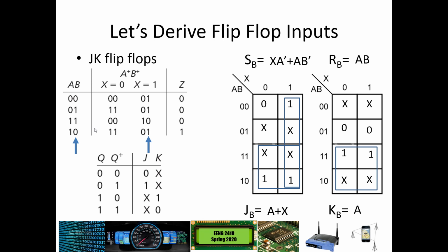And so this is why, and I emphasize this again, this may very well be a test question either on the final exam or test 2: the JK logic will always be equally as simple or simpler than the SR logic. And in fact, that is the reason that LogicWorks does not even give you the option of an SR flip-flop.